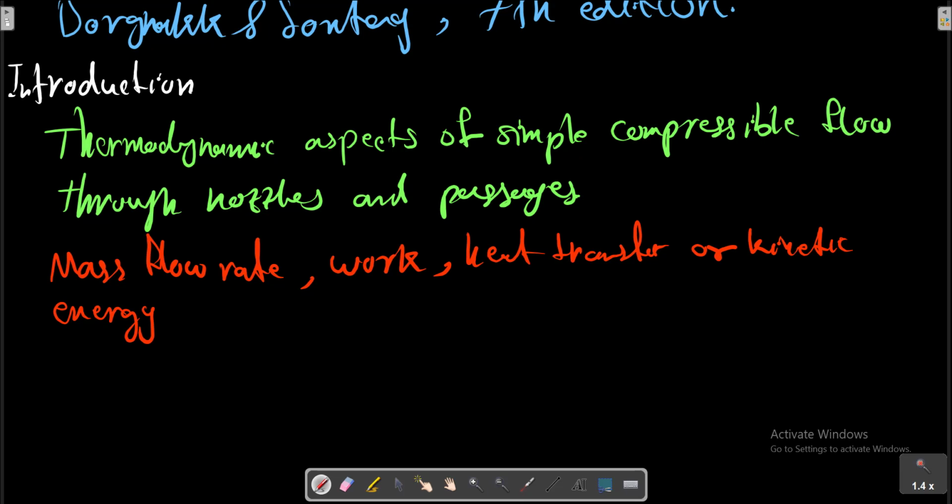All of the examples mentioned here are complicated with respect to the flow geometry and the flowing media, so we will use a simplifying model. In this chapter, we will treat one-dimensional flow of a pure substance that we will also assume behaves as an ideal gas for most of the developments. This allows us to focus on the important aspect of a compressible flow, which is influenced by the sonic velocity, and the Mach number appears as an important variable for this type of flow.